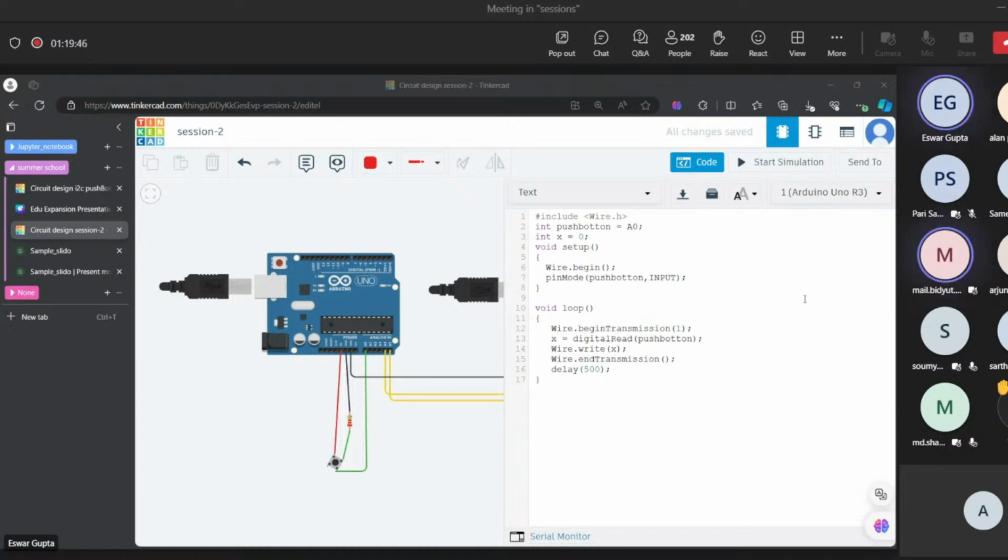Why is the delay at the end needed? Suppose you don't have a delay, and you pressed the push button, it recorded 1, and you have removed the push button. If there is no delay, the equipment will naturally have some slight delay, right? Suppose it has some 100 nanoseconds delay. If you just press the button and remove it, and there is no delay, when you have removed it, it will read as 0.